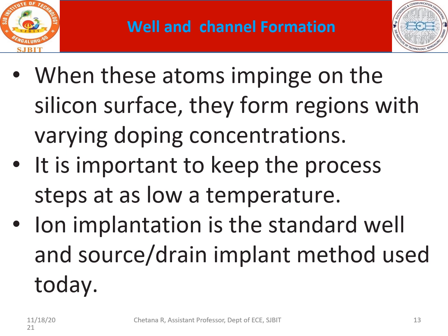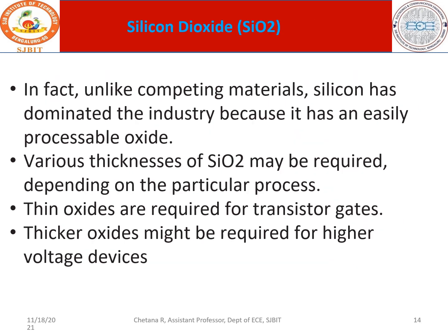In that furnace you make the respective gases form, and that is how the gases get deposited into the region which is exposed and not masked. That is diffusion. But ion implantation is very commonly used, which helps us to create source and drain regions. So that was all about your well and channel.